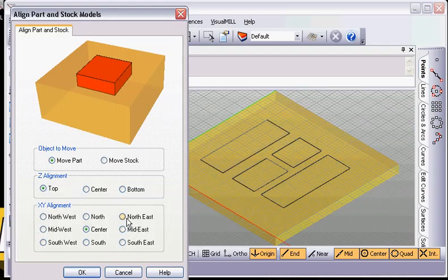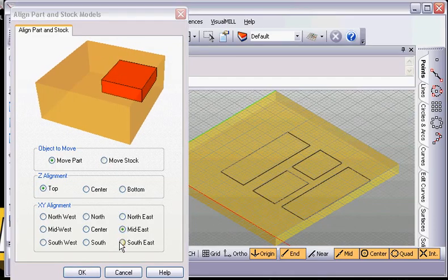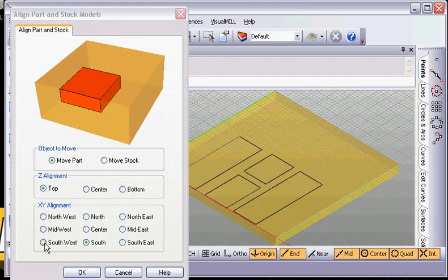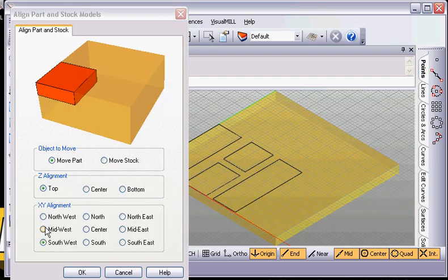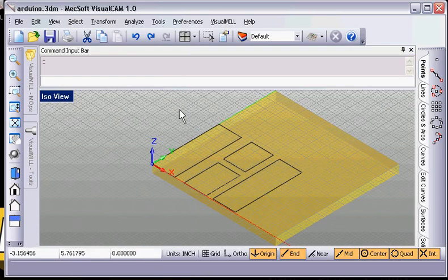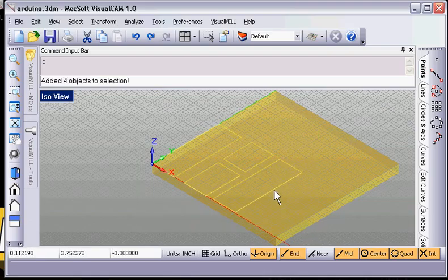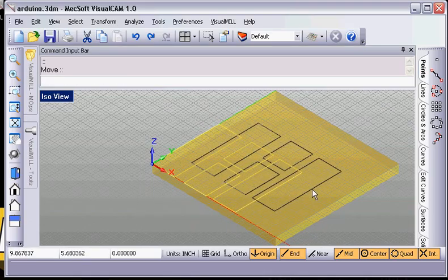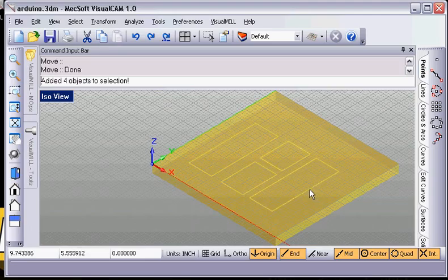If you'll notice the location of the drawing right now, as I move it around, we can put it where we want. We can also simply highlight our drawing and move it. Since this is a simple 2D drawing, I could move it out to here, and that would give me locations for clamps or tie downs, for instance screws, if this was a piece of plywood. Remember, this is our 0, 0 point, so we're going to set this physically in the machine and then move out from there.